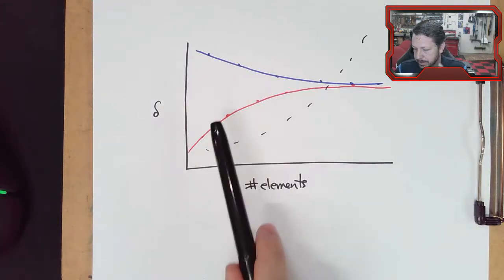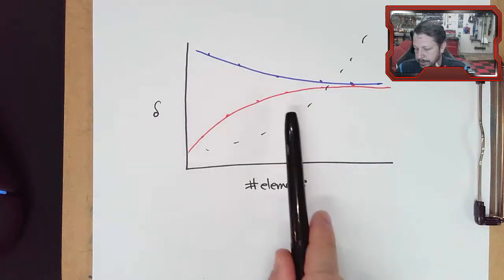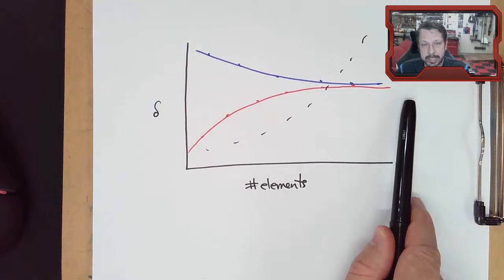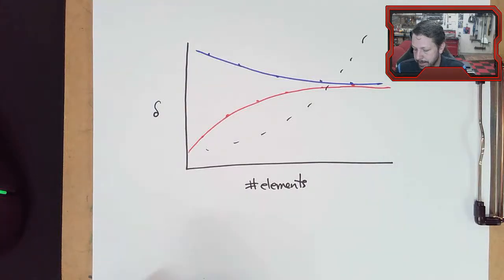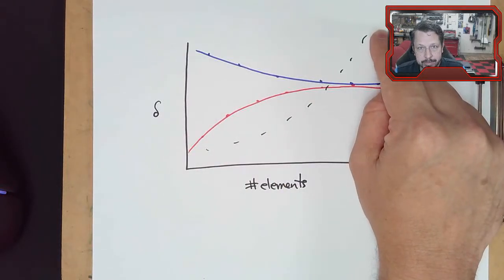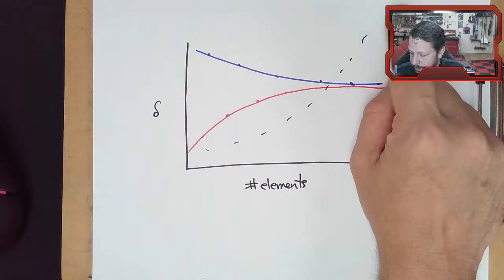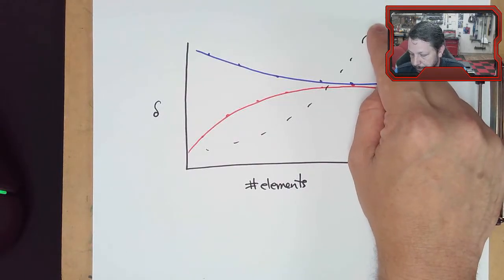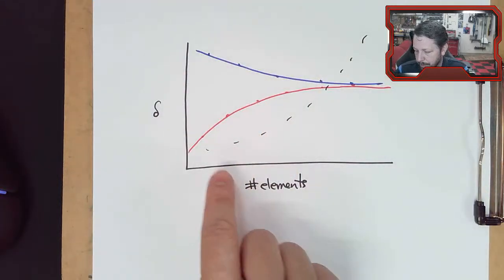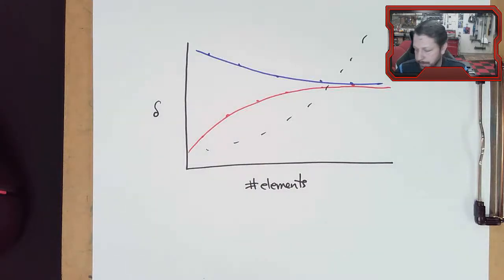And it's good to do a couple of runs at a low resolution, a medium, and a high, and see if there's some converging happening between those answers. Because it might be that you ran the elements all the way up to the maximum, you maxed out all the simulation parameters, and you've got this data point, but you don't have any history of whether you converge to that data point or if you are diverging. So that's a relatively easy way to have a model check against itself.